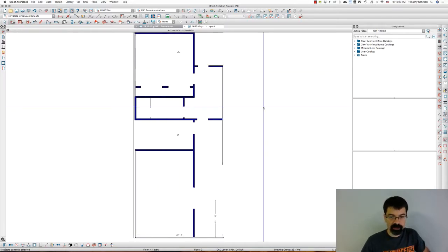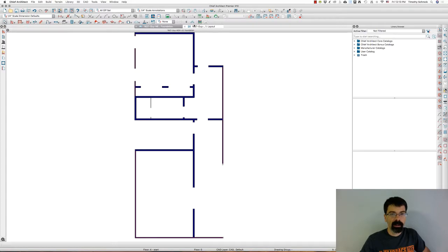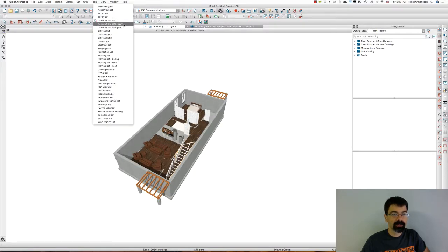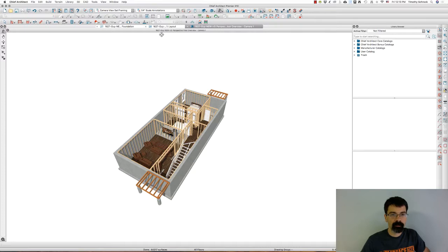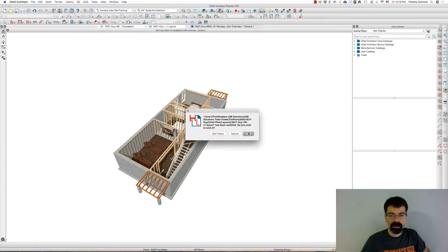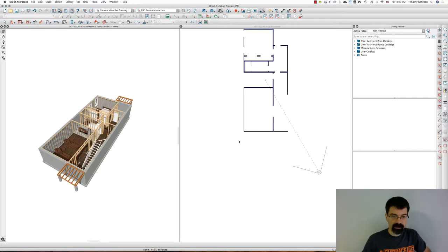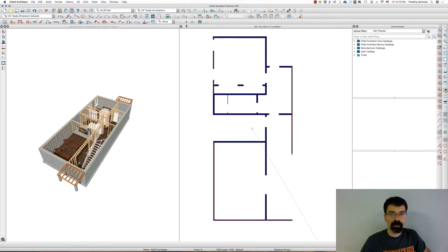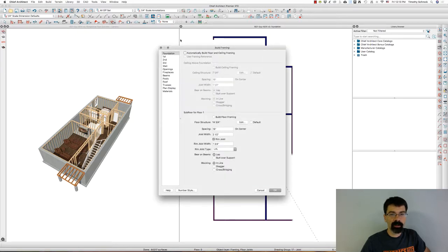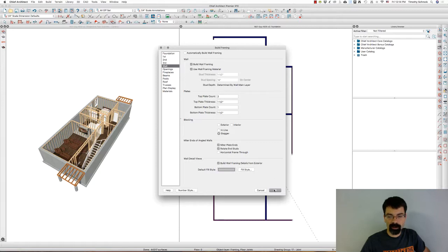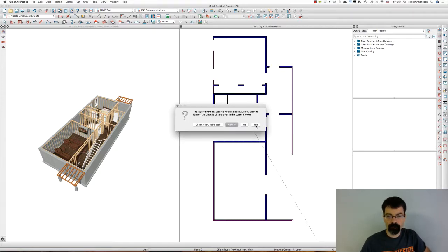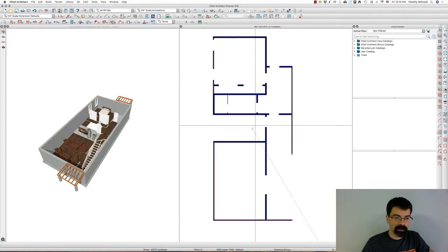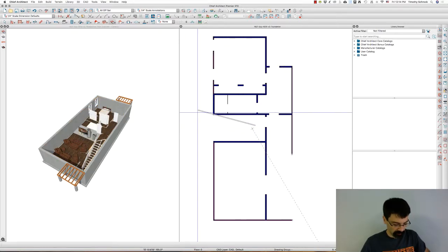Now, F6 to zoom back in. Now, let's go back to our camera view here. Switch to framing set. And let's turn this off, save that. I'm going to hit Shift F6 so I can see them side by side. And now, while I'm in the plan view, let's double click on my framing, build framing, go to wall, build wall framing, click OK. In plan view, framing wall is not displayed. Do I want to show it in this current view? That's fine. And now it is, escape.